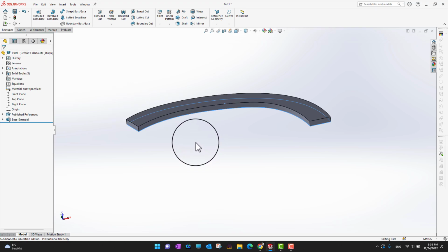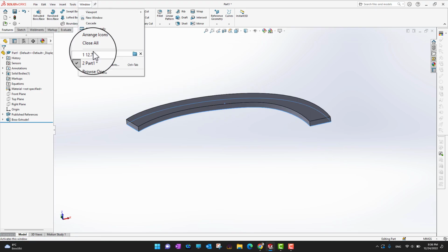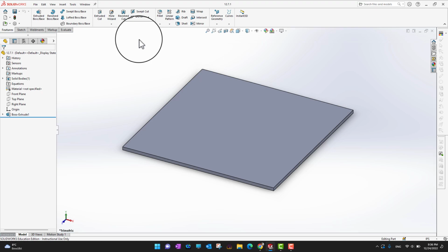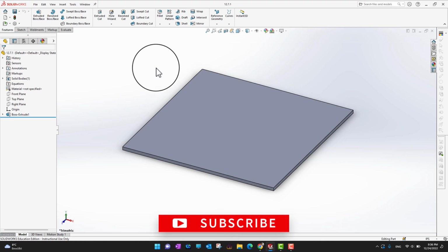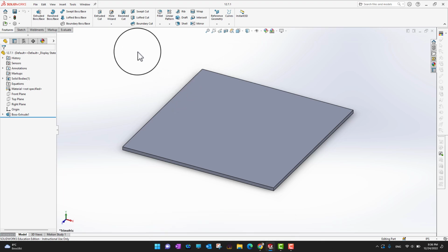So these are my first two connectors, and now there is another part onto which this part is going to stick. Let's go and look at another window. Right now I have this part, and I want to stick that part onto it and create multiple magnetic mates. As this is a part right now, I want to bring it into an assembly, and then create a ground plane on this part as well.